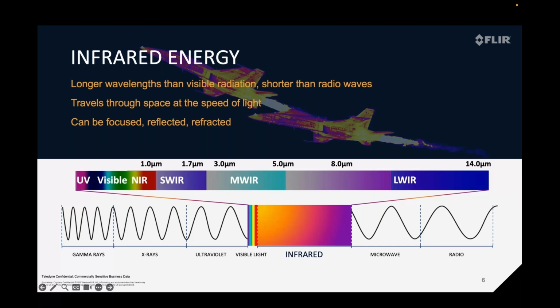And the next one, MWIR, or midwave infrared, is the region most common with cooled cameras. It's typically between 3 and 5 microns, but there's also broadband midwave, which is typically 1 to 5 or 1.5 to 5 microns. And this is where the thermal infrared band starts, in materials like indium antimonide, and then also MCT, or mercury cadmium telluride, it's always a hard one for me to say, are most often used as detector materials.